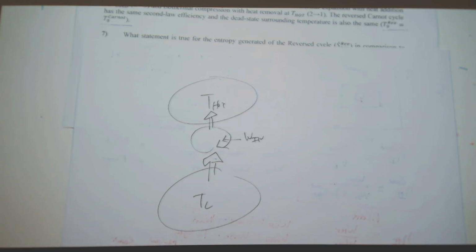So in principle, to go against the natural laws of nature, second law, I'm going to have a lower efficiency because I'm going against the natural trend. Heat wants to go in this direction. We made a refrigerator to go against the laws of nature. So we would have, in consequence, it would always be a slightly lower efficiency. Or with equal efficiency, that would mean we would have to have a system that would produce less entropy generated.